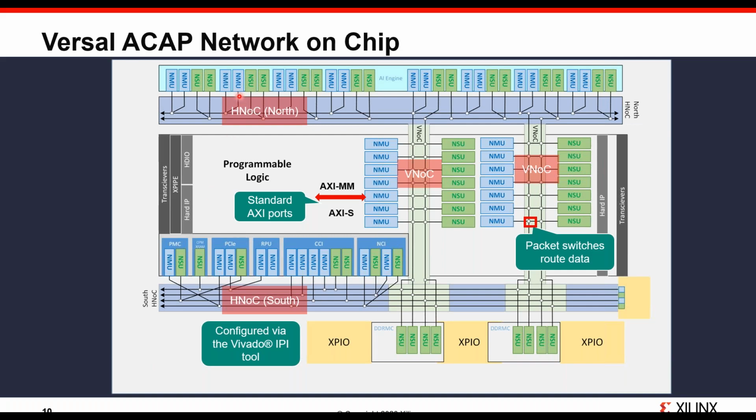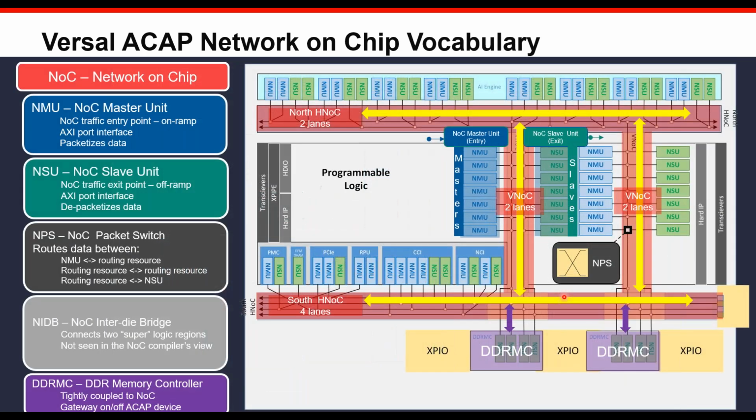So for the most part, you've got these horizontal and vertical paths that are, again, in silicon. They are built to be this, therefore they will run at these speeds. You've got the bandwidth available to you, it's what you do with it. So you've got the network on a chip, with the horizontals as we look at the yellow lines, and the verticals as we work our way through. Again, built to be up to 1080 megahertz or 1.08 gigahertz capability across those 128-bit channels, and 4 channels on the bottom, 2 channels at the top, 2 up the verticals.